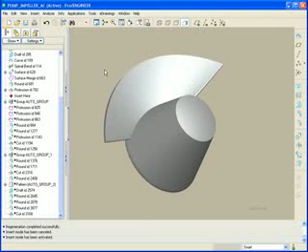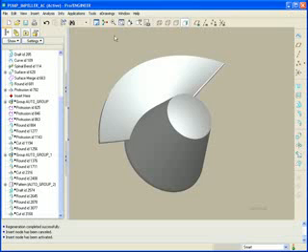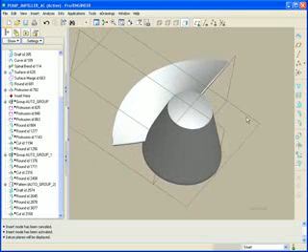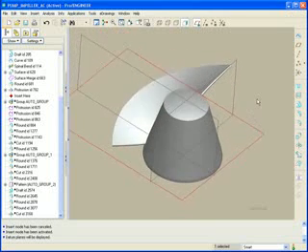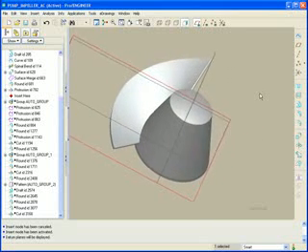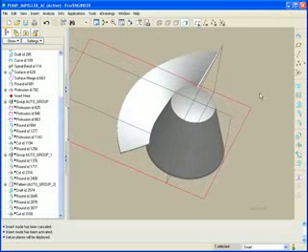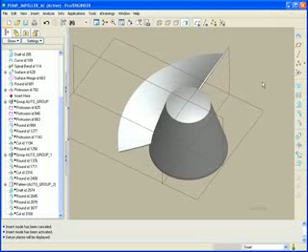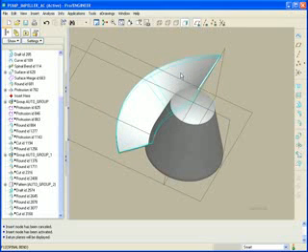How do we evaluate the slope, but not just the slope with respect to a plane, this bottom plane here? We want to evaluate the slope with respect to perhaps a flow line. So let's construct the geometry necessary to do that. First we're going to need a point on the surface someplace, then we'll need an axis that goes through the point that's normal to the surface, and then we're going to need to square it to the flow line.